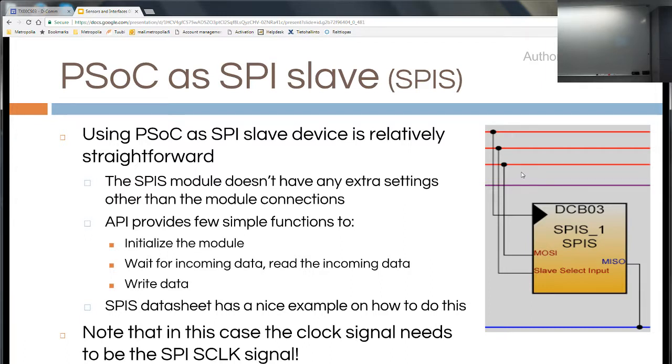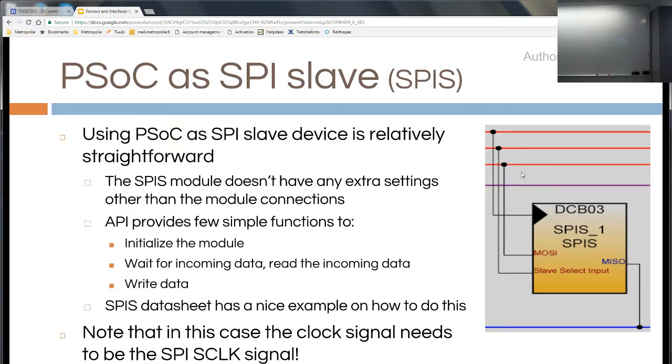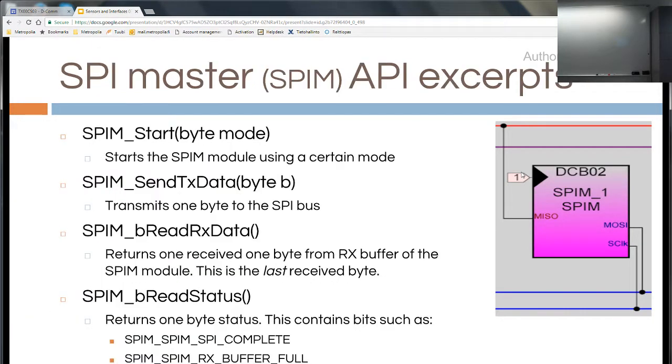Those hardware blocks don't have any buffers. Buffers you can do basically yourself by having this one interrupt when the transmission is over, and then it goes and saves into a buffer. But that's a software buffer.